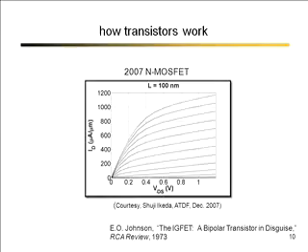Okay. So these are the IV characteristics of a MOSFET in 2007 that had a drawn channel length of about 100 nanometers, and a physical channel length that was a little shorter than that. So these are typical IV characteristics that you'll see for transistors.